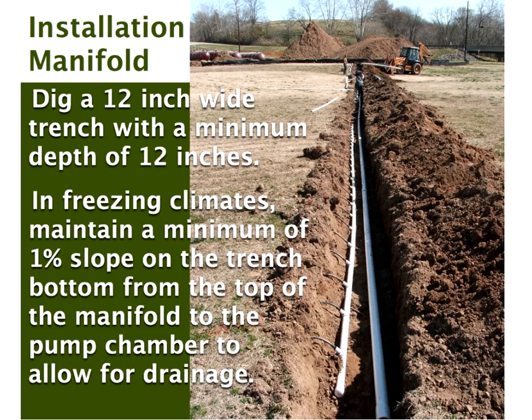Well, we have a number of sites that are using drip lines with just septic tank effluent. We do require a passive filter and also a filter on the pump, a Syntec filter on the pump, to try to filter out as much material as possible. Although after listening yesterday, it sounds like, because the applications that we've seen, we follow our criteria for soils, but the drip lines were 2 feet on center with, I think, 1 foot intervals on emitters. So after listening yesterday, it sounds like maybe we need to put more drip lines in those applications.